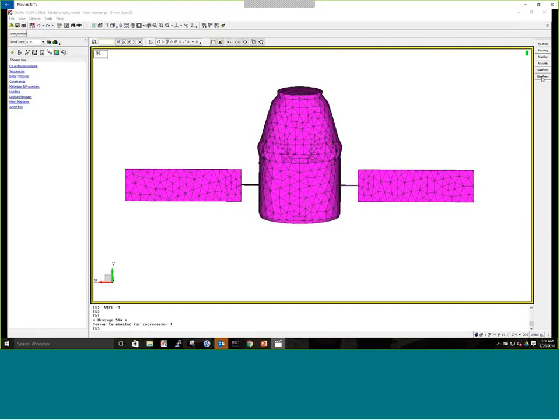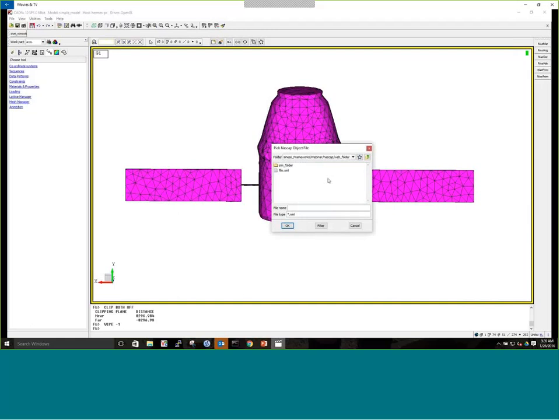So the user can go into this tool, and again, you define the set name that had all your surfaces, the same one we used to create the mesh. And then you pick the number of time steps in your simulation. So we had 200 in this. Again, you go in and select your object file. And this time we'll select the NTM file that NASCAP produces, which has time series data available.